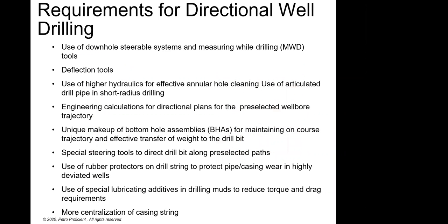So normally, in summary, what are the requirements of a directional well? Normally you have downhole steerable systems and measurement while drilling. You have deflection tools. You have higher hydraulics. You can generate higher hydraulics using a motor, which can help in better hole cleaning. Then you need to do some engineering calculations for directional planning, and we will come to that in the next few slides. So the engineering planning and all of that is a highly important part.